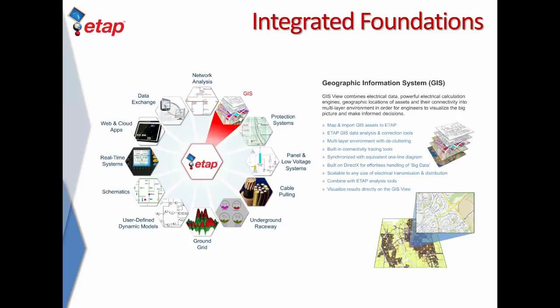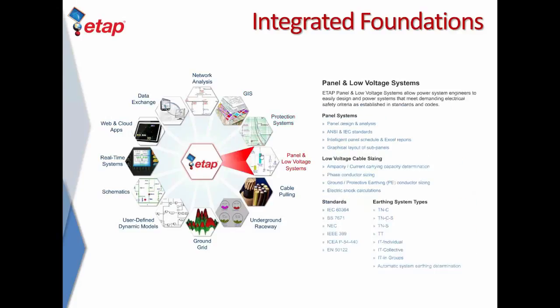There's an integrated protection and coordination program that allows you to model or include the protective devices and perform protection as well as coordination studies. You can go down to the low voltage network and model the three-phase, single-phase panel systems, do cable sizing, shock protection, using various standards such as IEC, British Standard, IEEE, and so on.